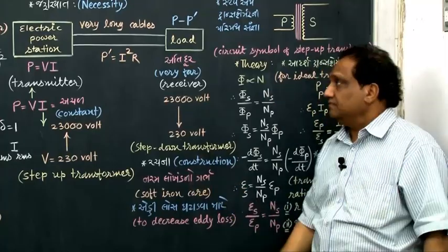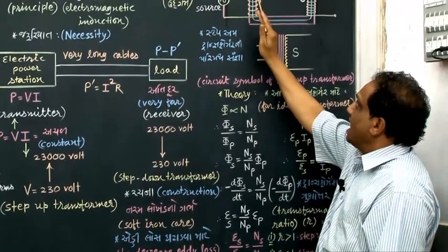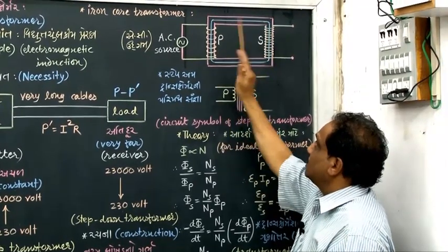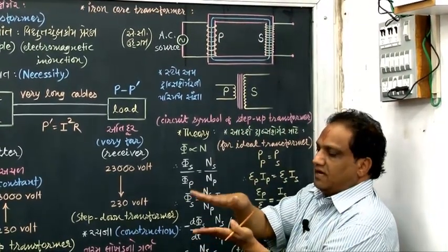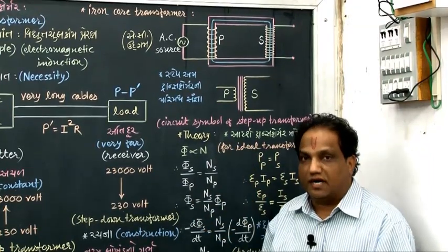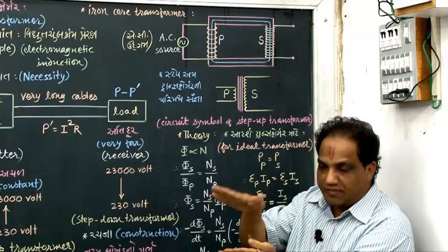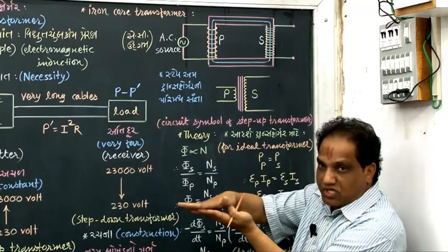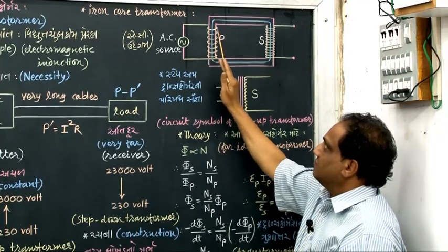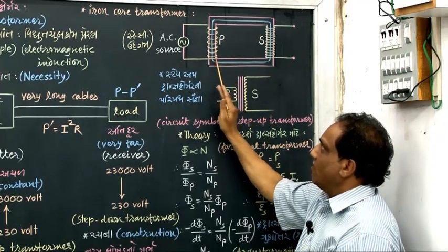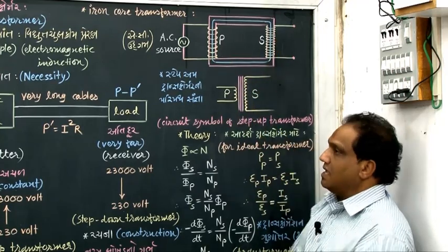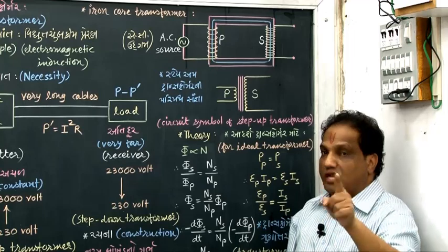Construction is very simple. We just take isolated soft iron rectangular strips, and they are electrically isolated by just providing a layer of some non-conducting substance over each of the strips, and we just prepare a bunch, and over that isolated bunch we just wind isolated thin copper wire at both the sides, both the opposite ends, and thereby we prepare two coils.